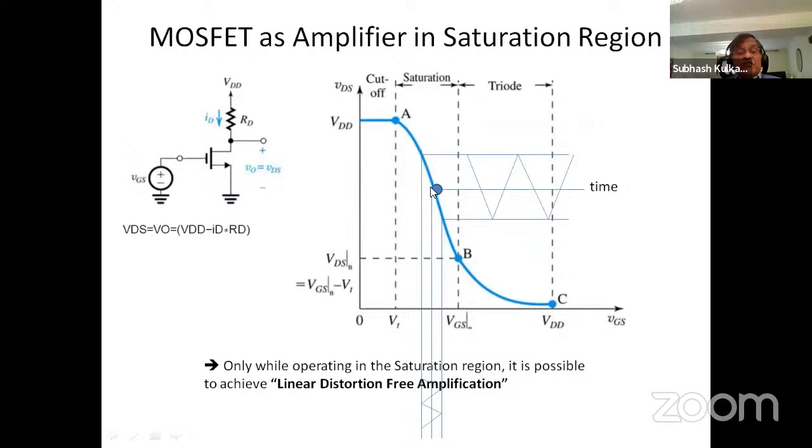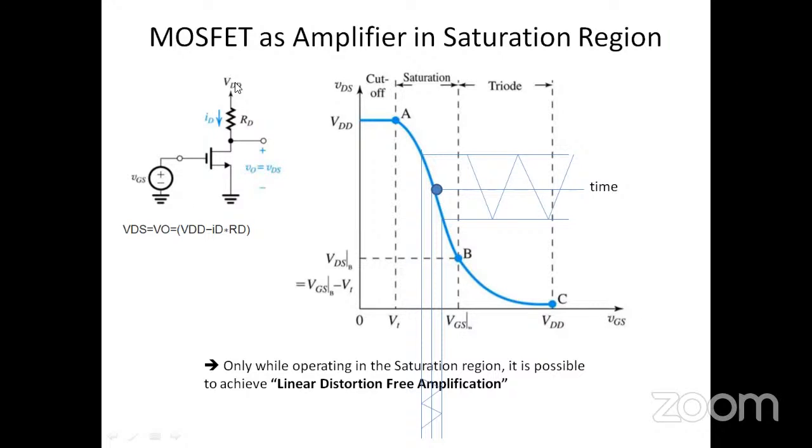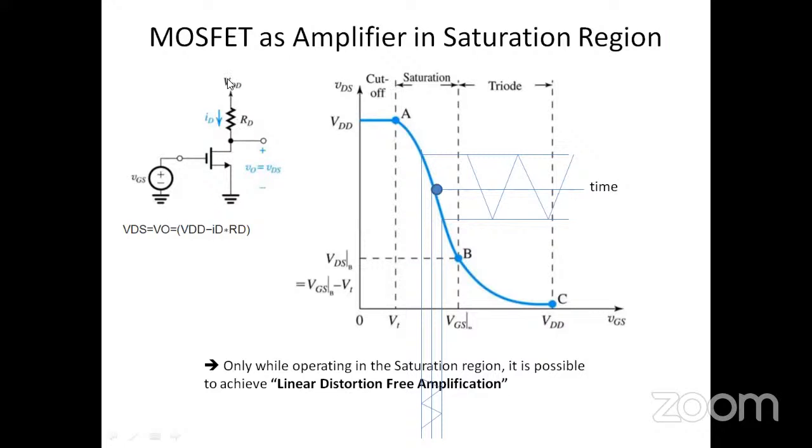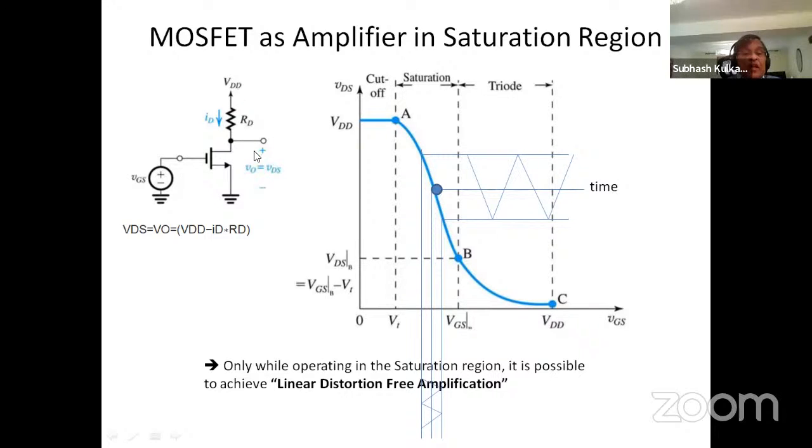Okay, here are the transfer characteristics of the same device. If you plot the output versus the gate voltage, and here is the electrical circuit diagram where you have the gate voltage, the transistor, and a power supply VDD, the output comes out of this transistor, which is VDS, and that output is plotted on the y-axis, and the input is your gate voltage. And here is a region where you're going through the saturation that I showed before.